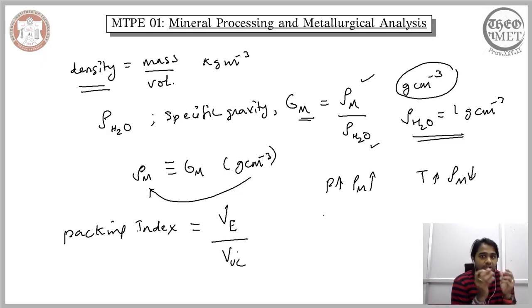In that unit cell you determine the equivalent number of entities that are present, calculate their volume, and then take its ratio with respect to the volume of the unit cell. You have entities that are occupying this unit cell, and you calculate the volume of these entities and then take the ratio to the unit cell.